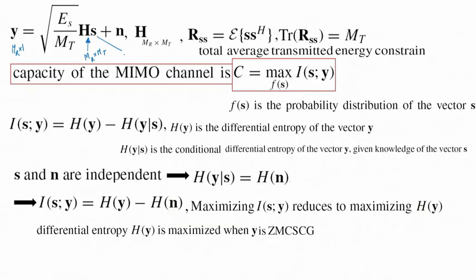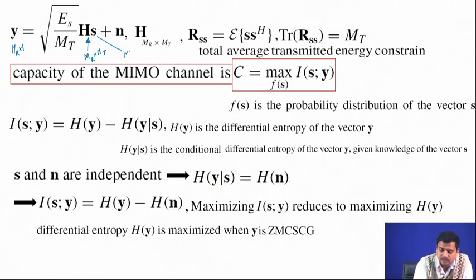This is what we have mentioned earlier: slow fading conditions and all the MIMO assumptions that we have made before. So, for a typical MIMO link, H is an MR cross MT matrix, y is an MR cross 1 receive vector, and S is an MT cross 1 signal vector. Okay. So, what we have is the received signal in its linear equation form.